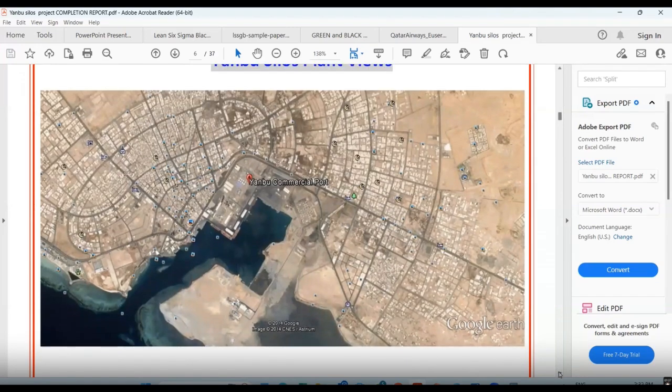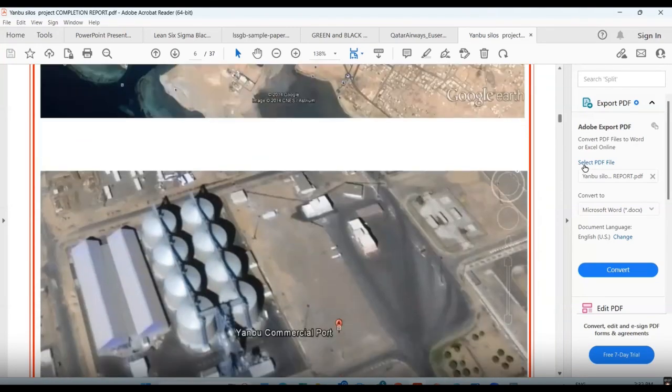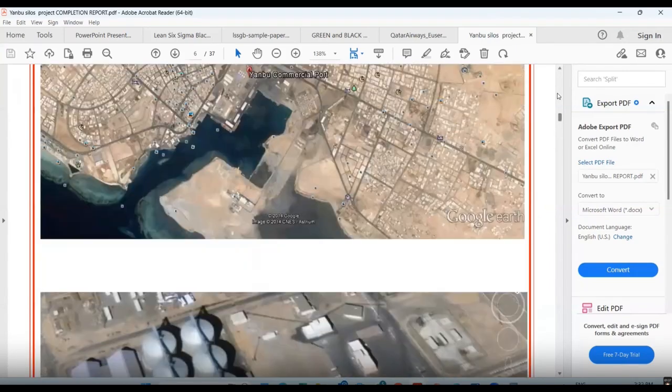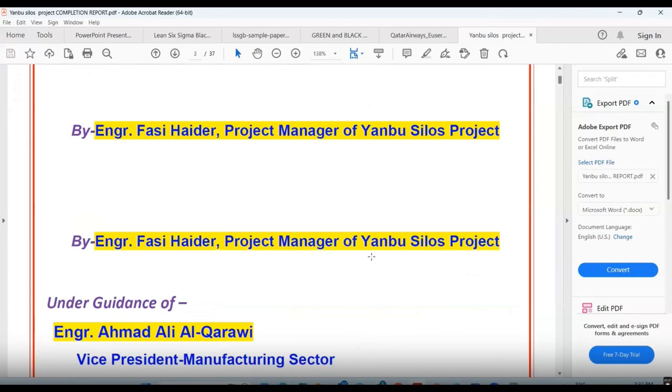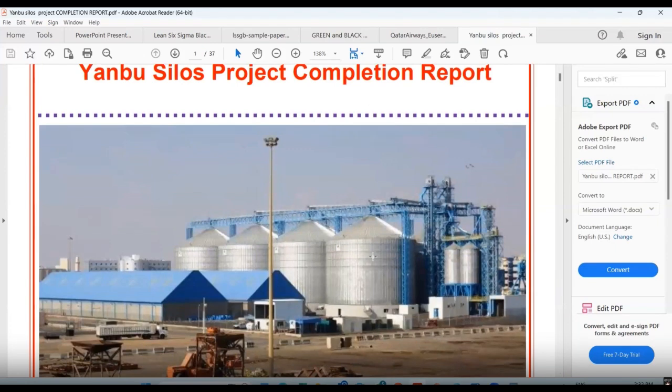Now, what has gone wrong? When we ordered this, the sheets that we have used are galvanized to 125. Galvanization means coating of a zinc layer on these sheets, which protects you from corrosion. But we had coated it up to 125. Now, when we did this project, it was fine. But after a couple of months, because it is at the sea, the surface of the sheets started getting corroded.